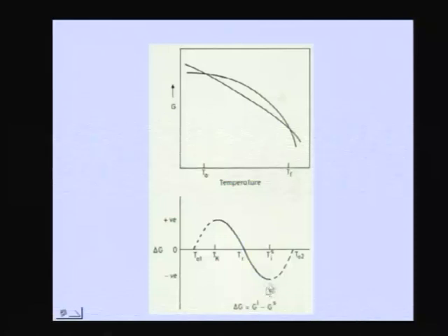For example, we have seen a number of cases, you can take a crystal, keep on bombarding it with some kind of ions, and you can keep on increasing the defect concentration in it, and as a result the free energy increases. The crystal will have a high free energy, but at the same time the entropy will be so high in the system that it can transform to an amorphous phase beyond a certain critical concentration of the defects. So though at the conditions here the free energy of the solid is higher than that of the liquid, we reach a condition where the entropies become equal, and once this happens the crystal